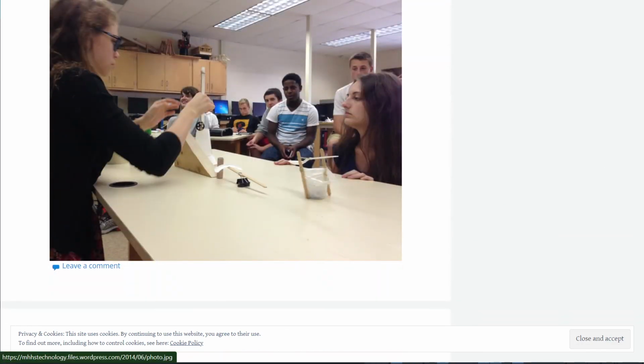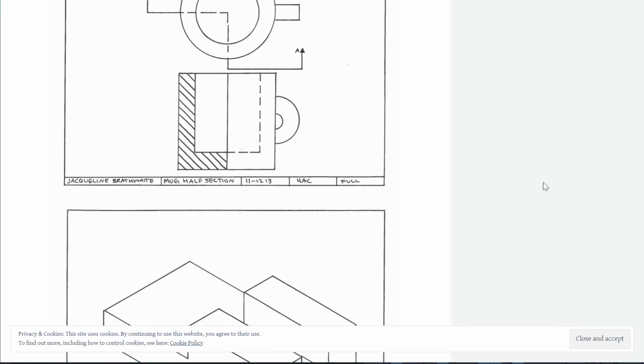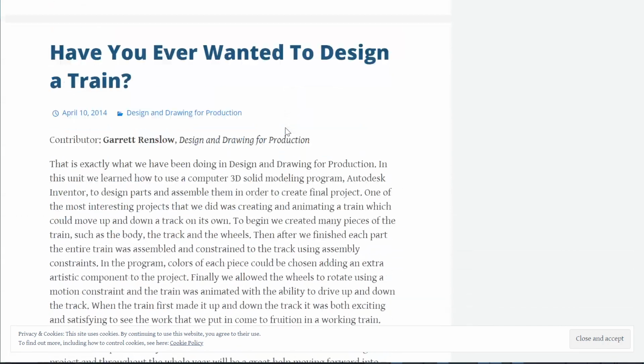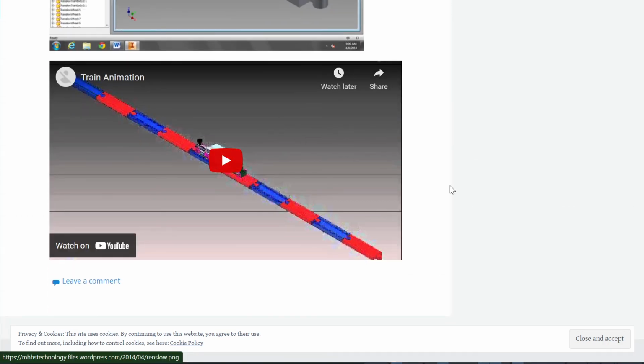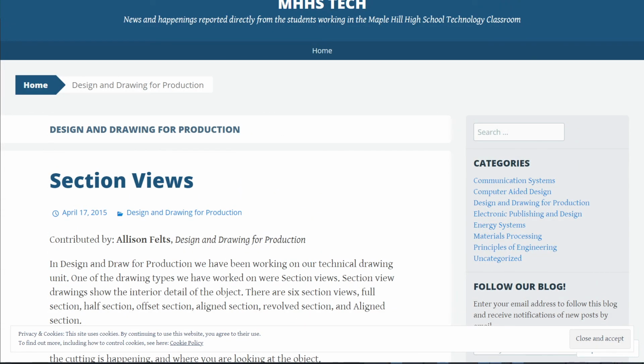It's also worth pointing out that you do get used to looking at objects in, I guess this is a half sectional view. So sometimes we only want to remove 1/4 of the apple, so that we show the full apple on one side. I probably wouldn't have shown, this is a coffee cup in this case, I wouldn't have shown the hidden detail if it were me, because we don't really want to combine hidden detail and sectioning. So, some good stuff there. Thanks, MH High School.